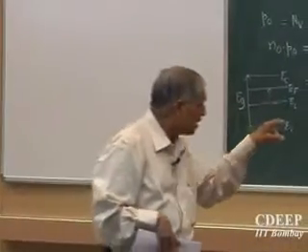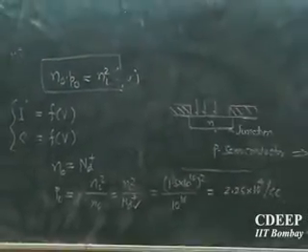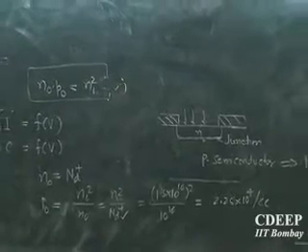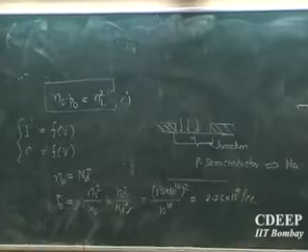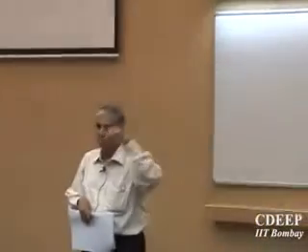So one can see from here, in the N-type material, how many holes do you have? 2.25 into 10 to the power 4 holes, and 10 to the power 16 electrons per cc. Therefore, you say N-type, N0 is much larger than P0, but there are not zero holes. There are finite holes. These holes are in the minority in N-type. Please remember, what are the majority carriers in N-type? Electrons. What are the minority carriers? Holes. Now, this minority carrier is actually the major cause of conduction issues.